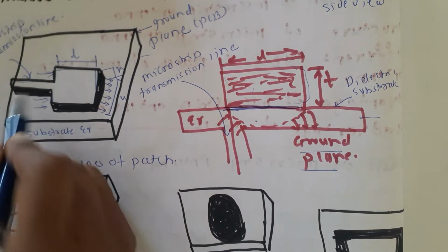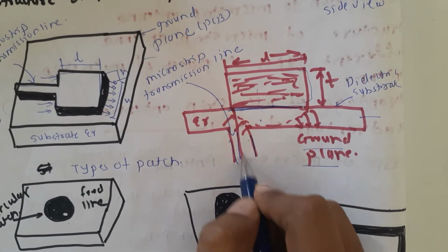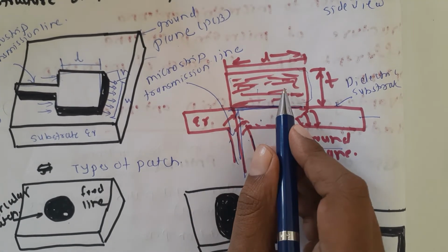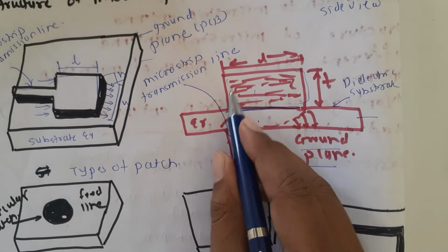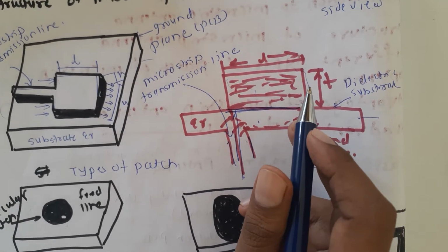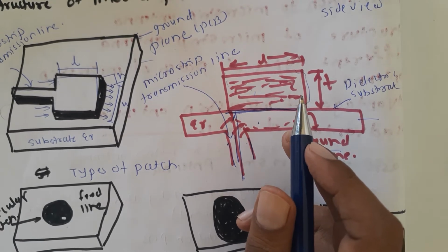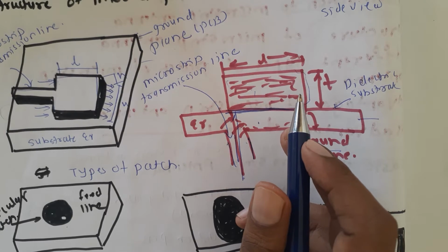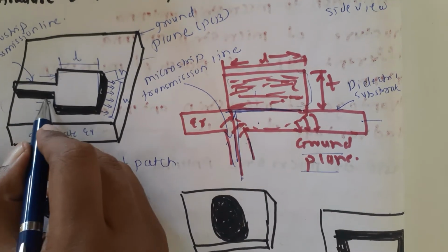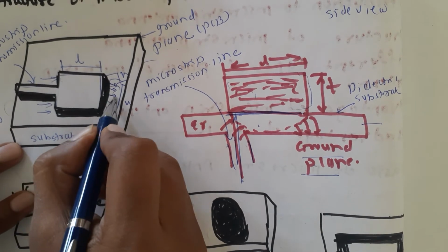Again here this coaxial feed should be connected to the ground plane, from where we apply the signal to this patch. After applying the signal, this antenna radiates. This type of antenna radiates on half planes, not on both sides of the plane. After applying the signal to this particular patch, it will radiate like this.